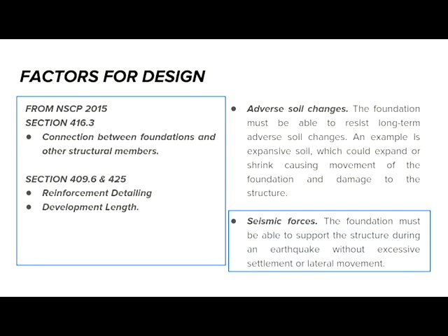Let's discuss the set of processes that we need to follow on how we are going to design. So first we are to decide on the dimensions of your footing.